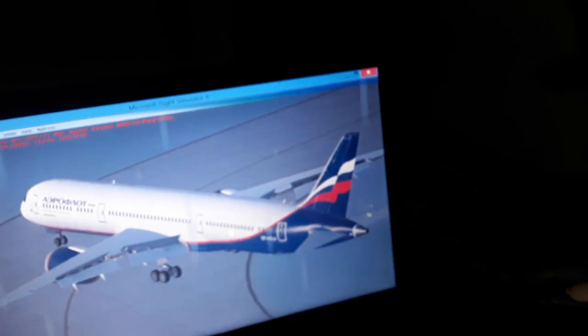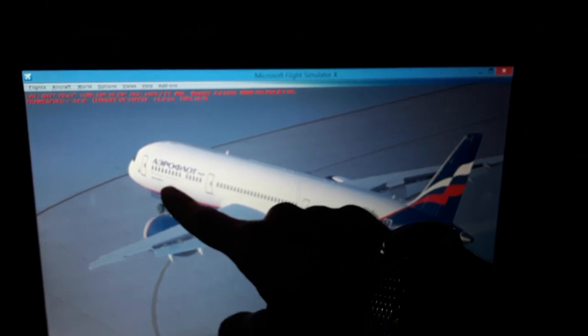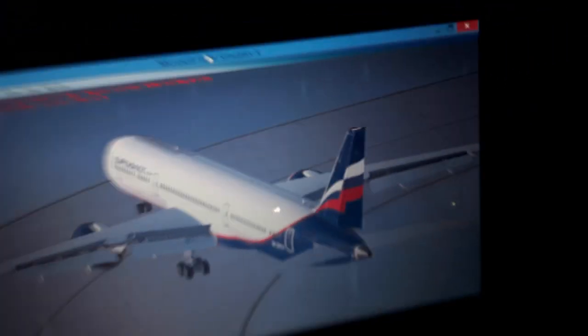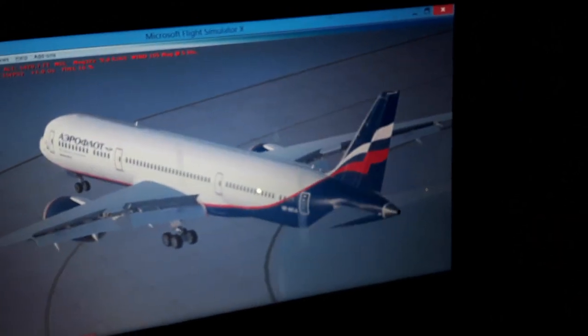above this airspeed of 45 knots. Then as we increase the airspeed for takeoff, or we are in landing, above 80 knots, the nose wheel steering is controlled to 0 deflection, is locked, and it cannot move left and right in either direction. So we have only the rudder to control the steering of the aircraft on the runway above 80 knots, or about 140 kilometers an hour. We have only the rudder. Below 140 kilometers an hour we also have the nose wheel steering, and it increases as we decrease the airspeed. So this is the inverse when you land.